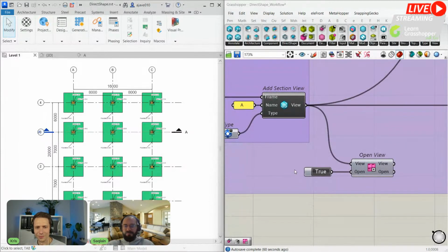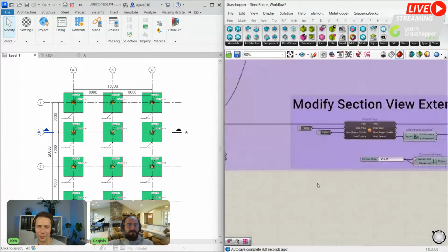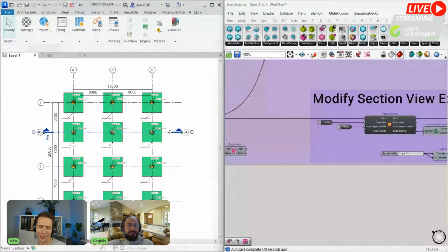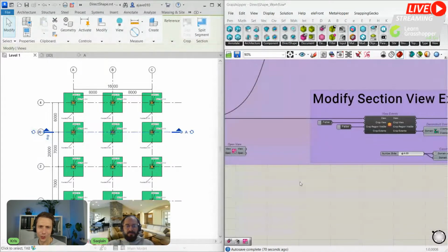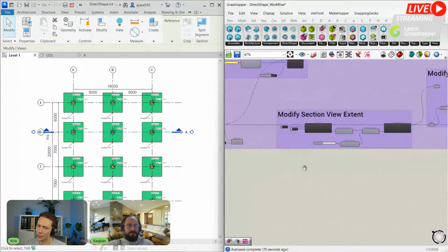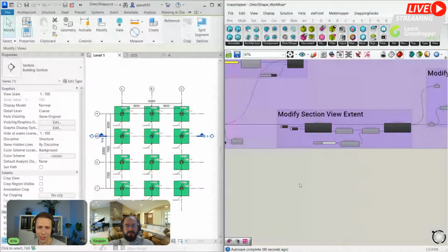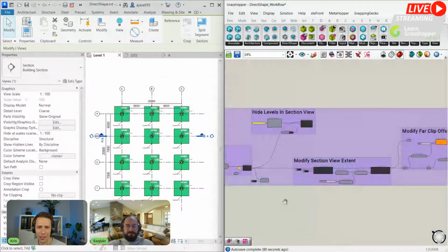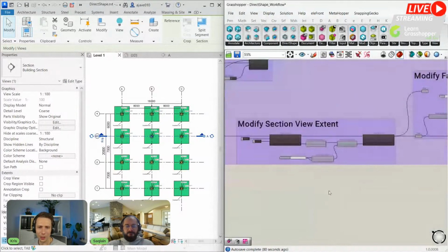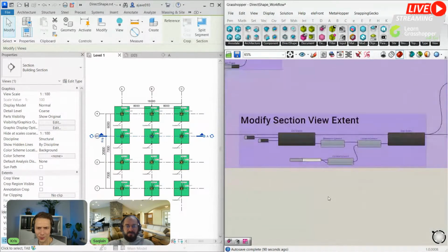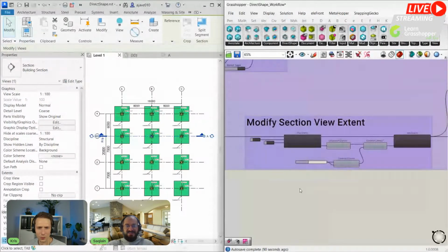And we are showing just one section, but you can imagine that if you are going to create like 15 sections, you can do it in the same way. It will automatically create for every one. This is a really simple structure, and for sure you will need maybe 2, 3, 4 sections. But if you have something in curve or you need more sections, then you can actually create all the sections automatically. Yes. So basically I set up this workflow because we had this restriction that we have to create this section at specific locations. So I had that location every time I was running the workflow.